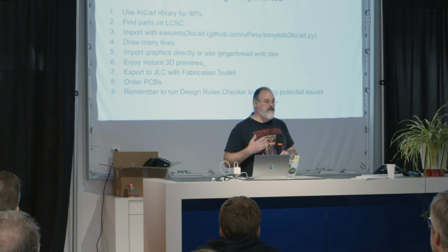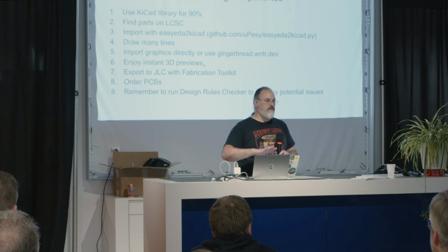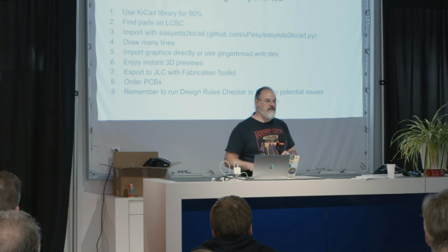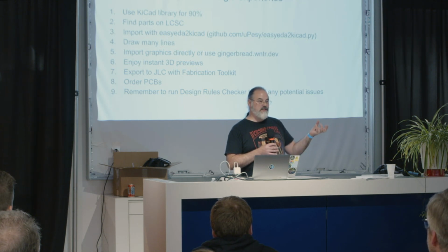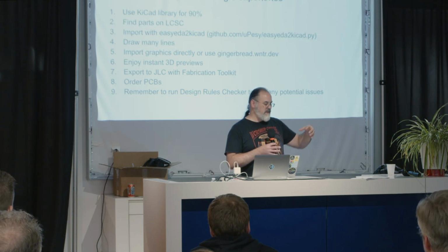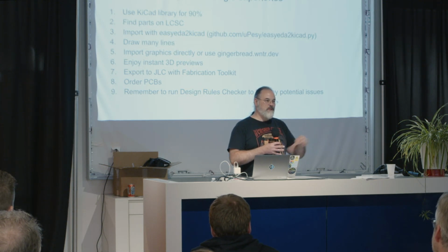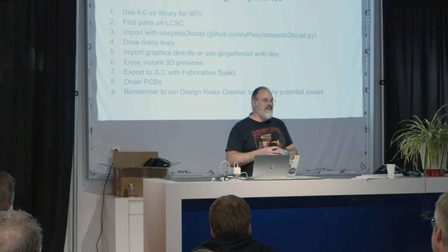And then instant 3D previews. Again, before this, I was like, yeah, whatever. I don't need 3D, all this kind of stuff. But having your board right here update live while you're placing stuff and seeing, oh, wow, this connector is really big. Or if I intend to rework this, maybe I shouldn't put the little tiny thing with the little pins in between this valley of giant components or something like that.